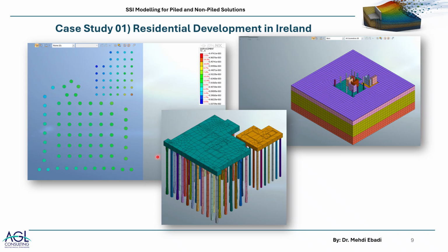So then there are different ways to extract the loads per pile for these, which we did. And for settlements, you can simply, like what I did here, extract the settlements of the piles, which were in this case generally less than 10 mil or up to 10 millimeters.